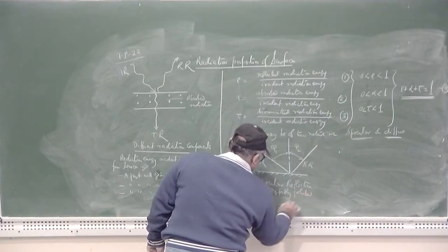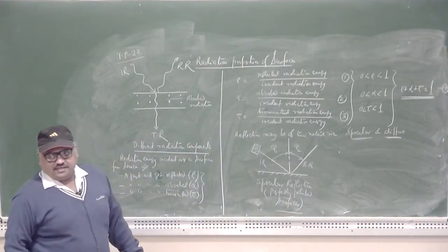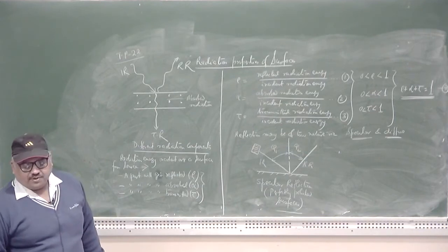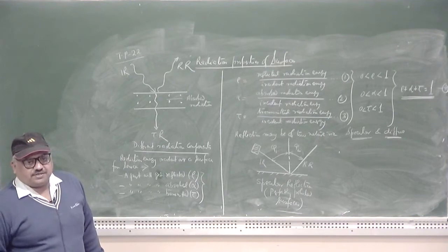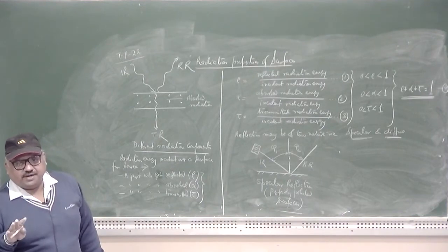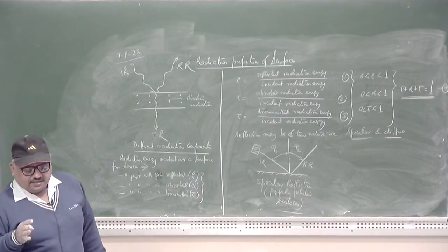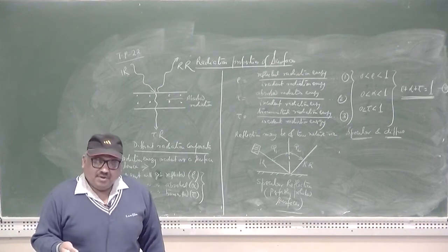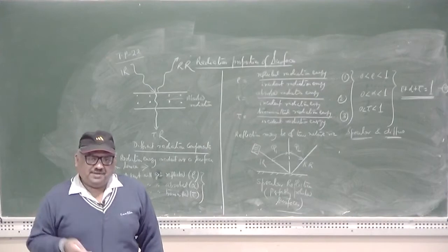polished surface. In the preparation of metallurgical samples to be studied in the compound microscope in the metallurgy lab, it is often customary to have an almost 100% specular type of reflection, so that the phases which are there in the microstructure may be completely revealed to the observer in the eyepiece.